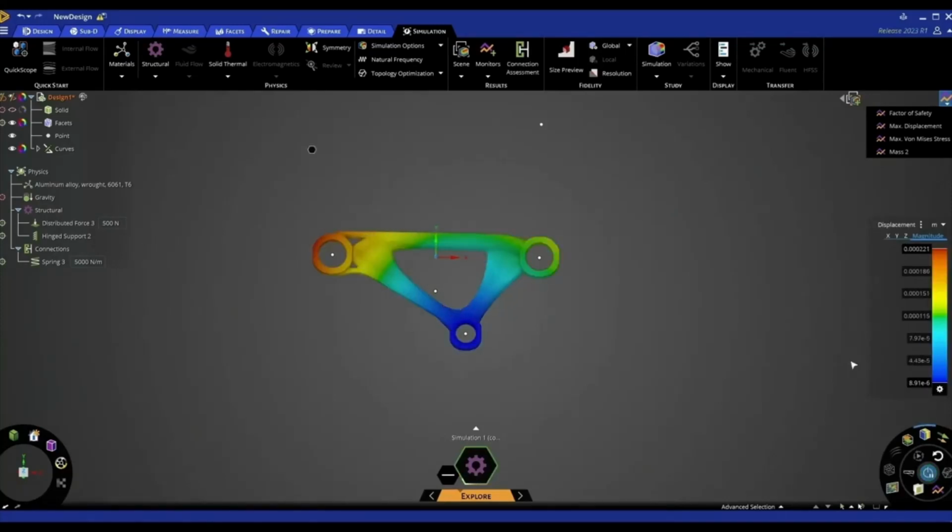and you'll notice obviously what we're doing here is actually solving on faceted data. So this isn't actually solid data, it is actually faceted data. Again, that is sort of different. Again, we can see that we've got a factor of safety of 45.9. I think that was reduced from around 65. So a decrease, which we sort of would expect because we are reducing the amount of weight.